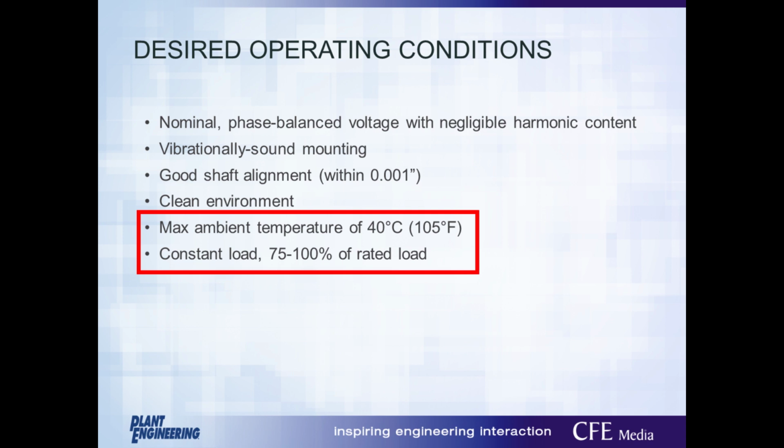One thing you may notice is that most low voltage motors are rated for 230 volt, 460 volt, or 575 volt operation, even though typical low voltage distribution levels are 240 volt, 480 volt, or even 600 volt. You may be wondering about the difference. The 10, 20, 25 volt difference accounts for the voltage drop in the distribution lines into your facility and then within your facility. Slight overvoltage at your motor leads is all right. It's not generally that much of a problem.